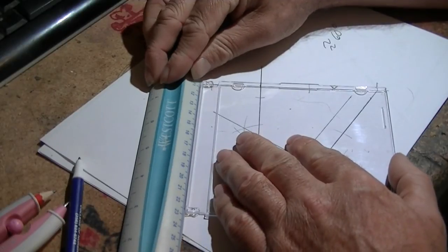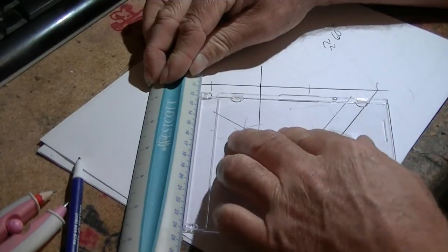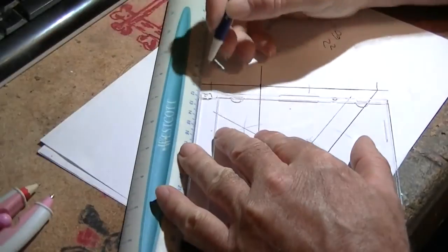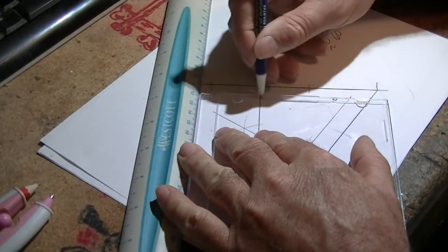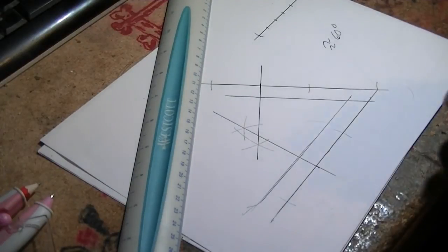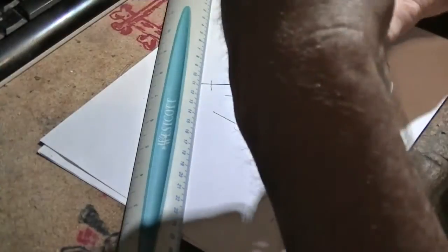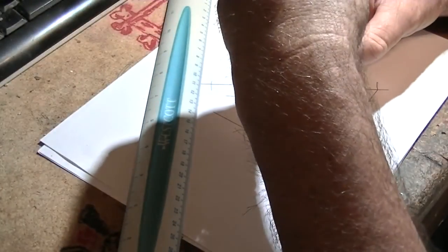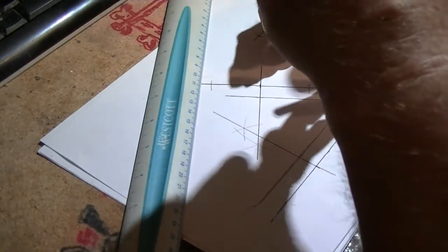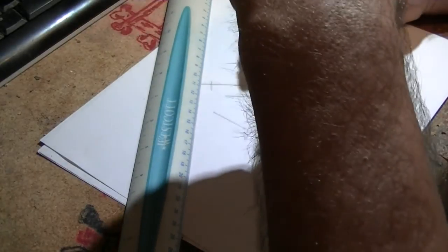Okay, I'm on my line. I have my ruler butted up against it. I slide up to the tick mark and I draw my parallel line. Okay, and we have a good cross. Now my compass is already set for 1/2 inch, so when I draw right on that cross point, I should have a good tangent,